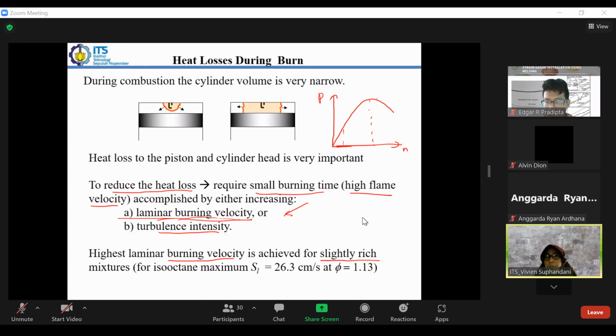So we can define, for example, for a certain speed, when the camshaft opens the valve, as well as the spark plug timing and how much is the composition or the injection, how wide is the throttle opening and so on. That is all controlled by the ECU, the engine controller unit.